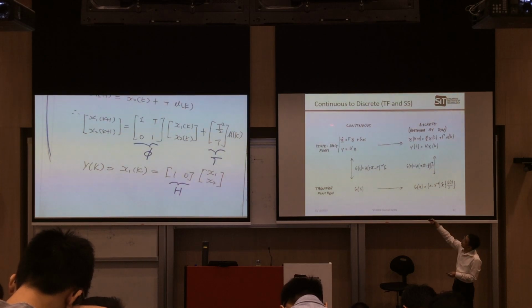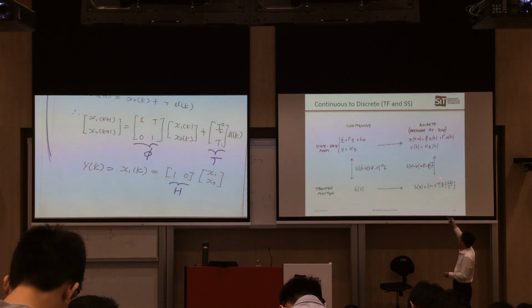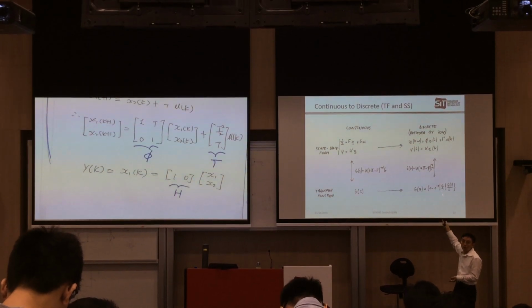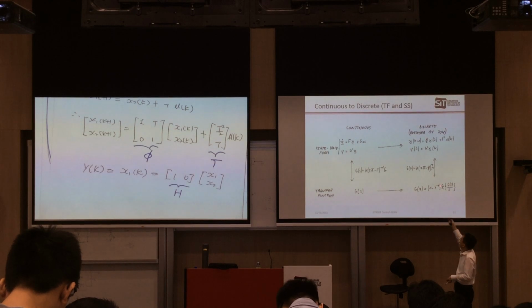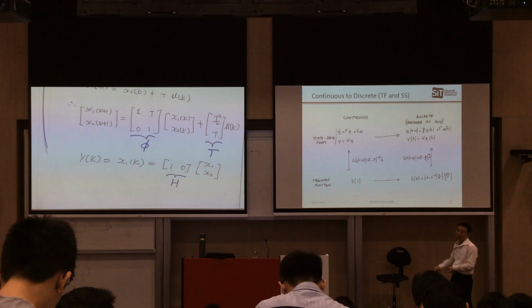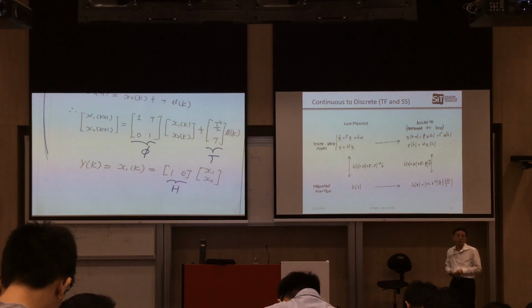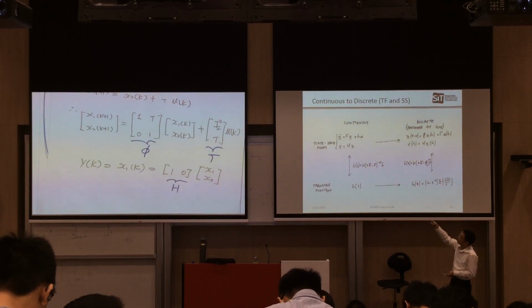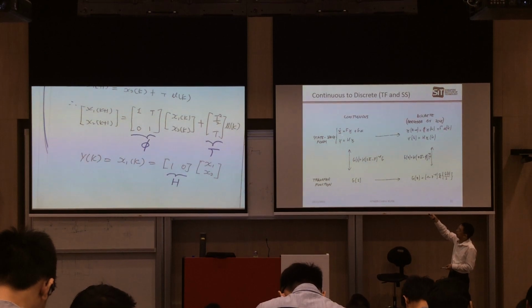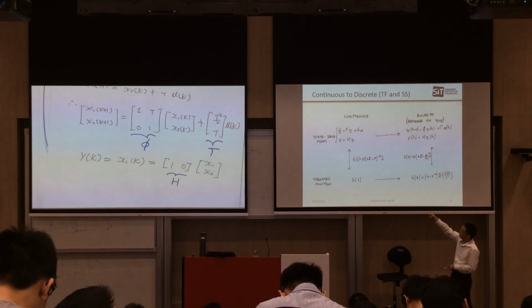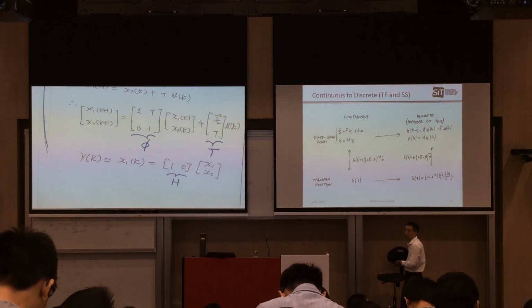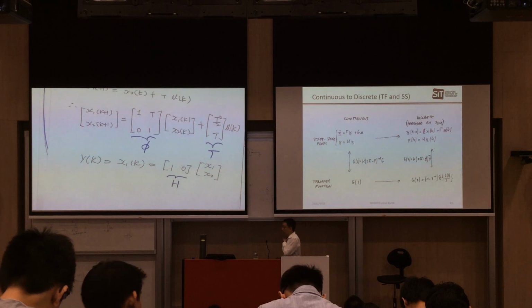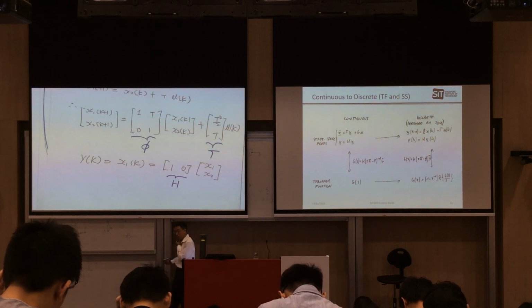But of course, if you already have your state space function and you want to digitize it, then you just do this one. You're not supposed to do this and this. If you already have your digital transfer function and you want to find your discrete function, then basically you will go back to the difference equation, then from the difference equation you get your state space. It's a similar step as in the continuous domain. You get a differential equation, then you represent it in state space. So basically your state space is a form to represent your differential equations, or your difference equations.